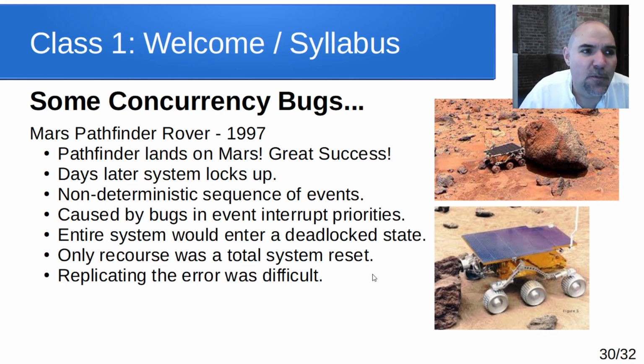They eventually were able to replicate it and figured it out, and then uploaded new firmware to it remotely, and it was successful at that point. But again, imagine that if they hadn't built in a watchdog timer system to reset it, they would have spent all this money sending it up there, and because of a single concurrency bug in the system, the whole thing locks up and becomes a brick at that point.